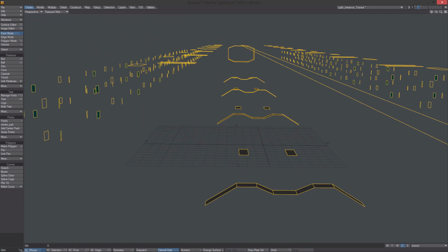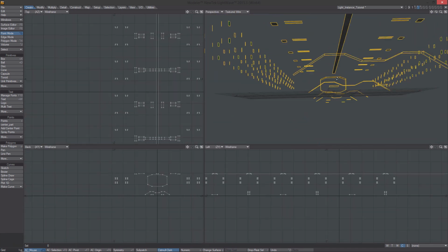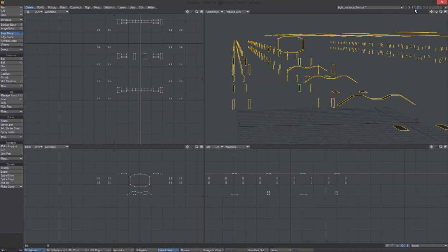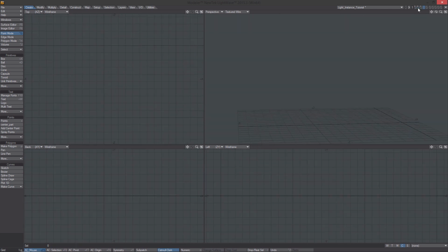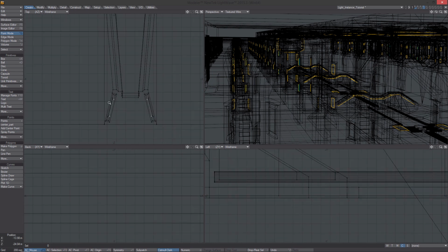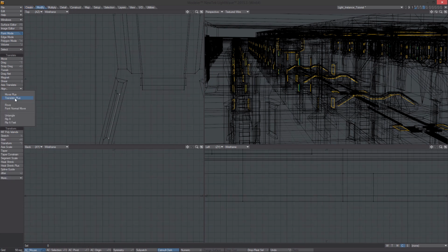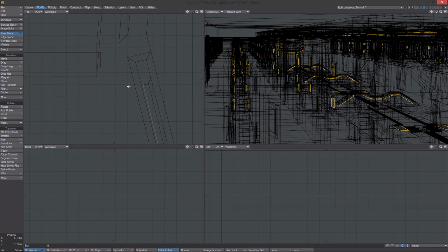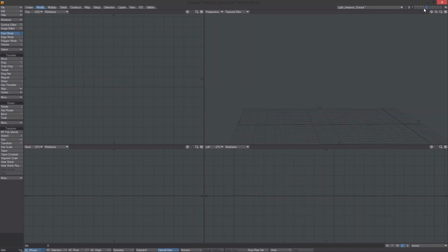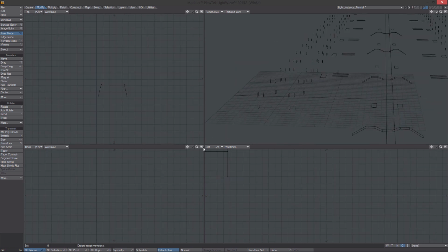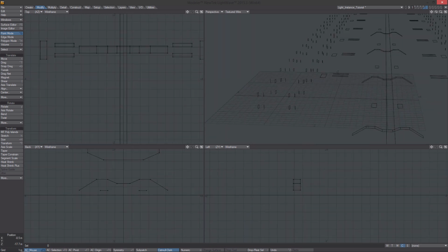What I did was I took all the luminous surfaces and put them on a new layer so that they would be separate from the other layer. That's important because we don't want these casting a shadow. I copied them and put them into another layer. On this layer, all I'm going to do is point normal move the points so they're a little bit behind the actual polys that made up the luminous geometry. I would have gone a little further, but that one section was determining how far I could go because I didn't want it to intersect with other geometry.